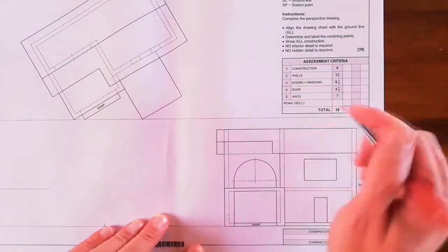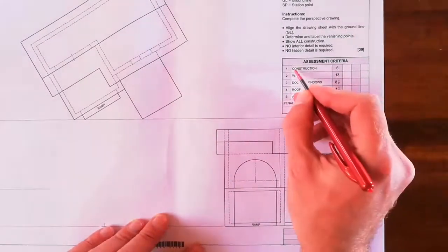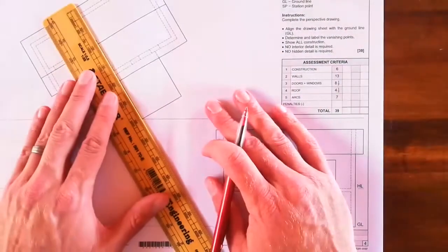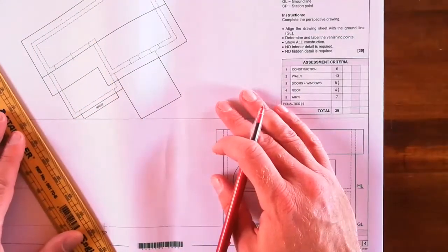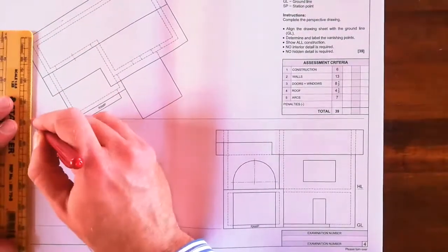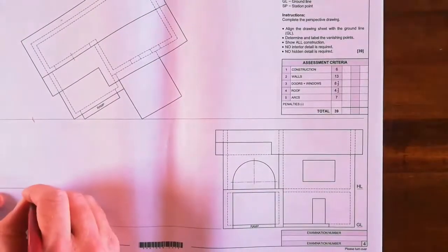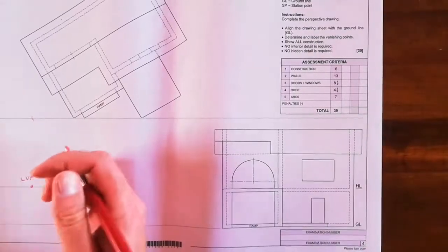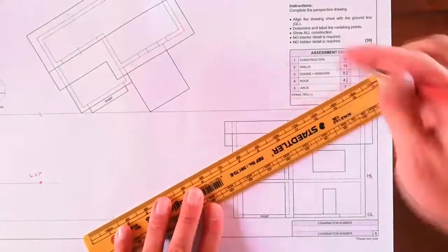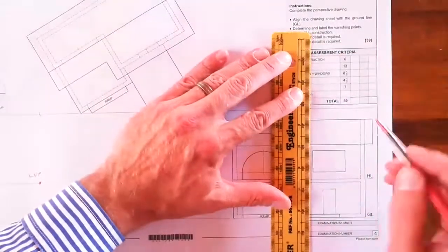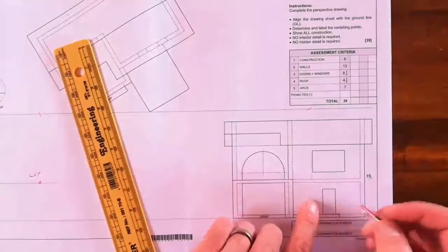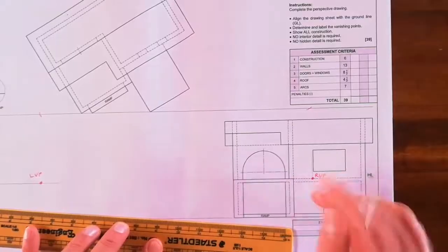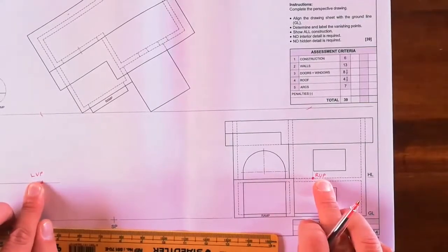Okay, let's look at this. Again, on the assessment criteria, it gives you some indication what they're looking for. Construction, 6 marks. Ladies and gentlemen, that is to determine your vanishing points. I'll just do this roughly here, okay? It's this dot plus labeling, left vanishing point. Same with your right one, parallel from the SP to the picture plane down. Don't think it's wrong because you're here in the middle of your drawing, okay? Mark it clearly, right vanishing point. That's marks, that's marks. If you don't label it, no marks.